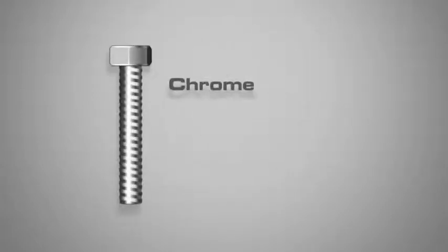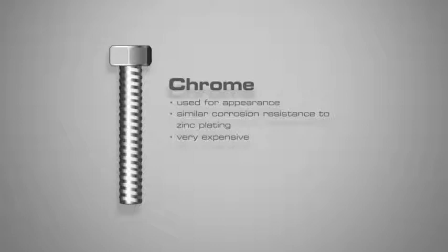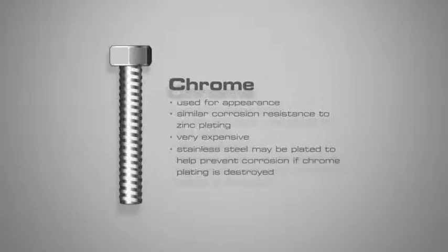Chrome is used in plating fasteners for its appearance. It provides similar corrosion resistance to zinc plating. Chrome is very expensive, and this is the main drawback of chrome plating. If more corrosion resistance is needed, then stainless steel may be chrome plated, so if the plating is destroyed, the bolt will still be corrosion resistant.